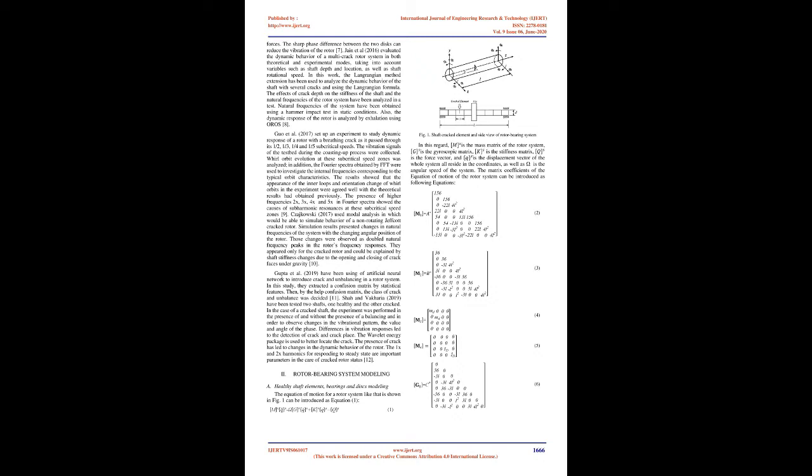Swilin Chen, 2016, examined a finite element model of a rotor system with a slant crack and 2 disks. 2 types of linear and nonlinear bearings were used to simulate bearings, while the slant crack was modeled with time-variable stiffness. In this paper, the effects of the 2-disk eccentric phase difference have been evaluated on the nonlinear responses of the rotor bearing system in steady state operation and starting operation.